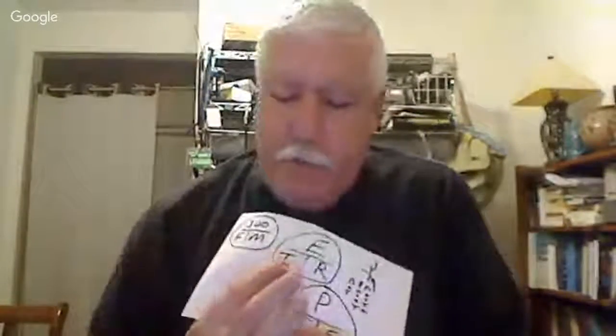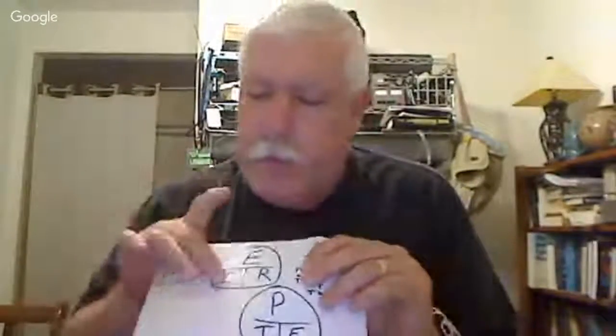I'm going to skip forward a little bit. T5D08 on page 161. All right. Okay, we're back on our solver. What is the current flowing through a 100 ohm resistor connected across 200 volts? So they're asking for current. Cover the I. There we go.